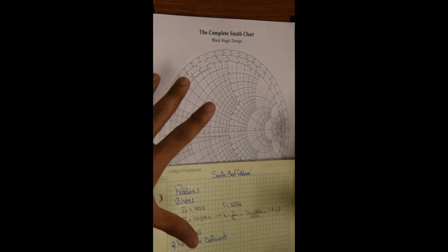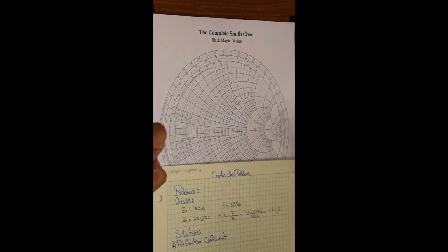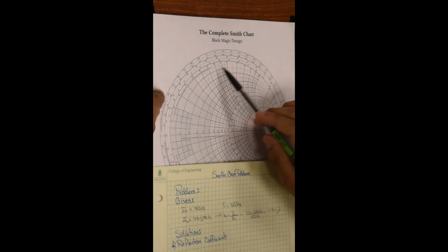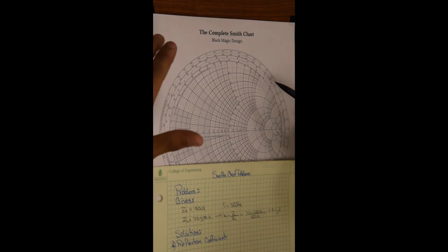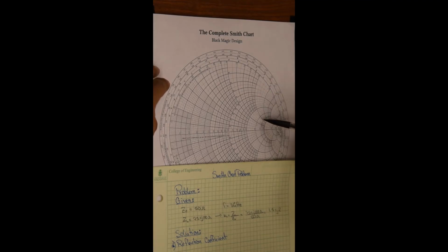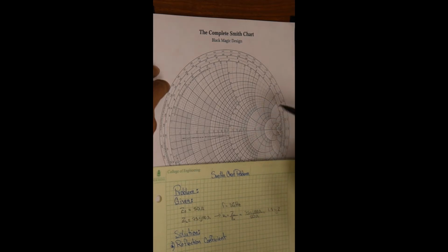Since it is positive, we will locate it in the top part of our Smith Chart. So let's find where on this axis is this positive 2. As we see here, we have 1.8 and 2. This is the number that we are looking for. And the normalized impedance will be the intersection of the line coming from these two and the line coming from the 1.5. So it will be this point right here. Again, our normalized impedance will be the intersection between the 1.5 and the j2.